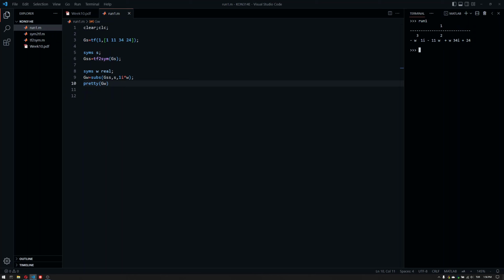Now, of course, when we substitute a complex variable into the transfer function, which is just a division of polynomials, we get a complex valued function depending on omega. And if we look at it like this, we are looking at it in Cartesian coordinates. That's not really common because we cannot really see what it looks like or what it even means. So we like to transition from Cartesian coordinates into polar coordinates. If you're in polar coordinates, stuff becomes clearer.